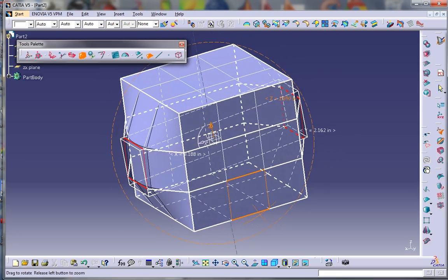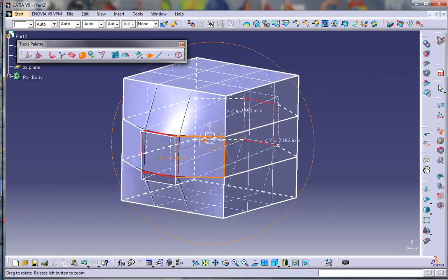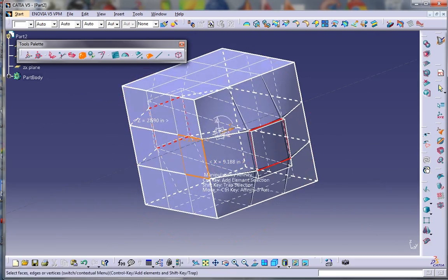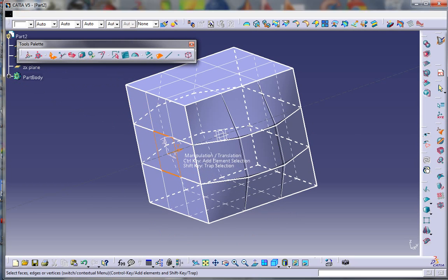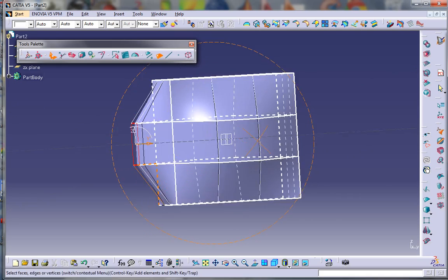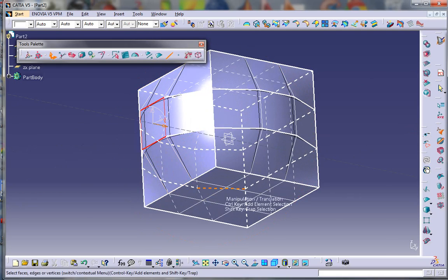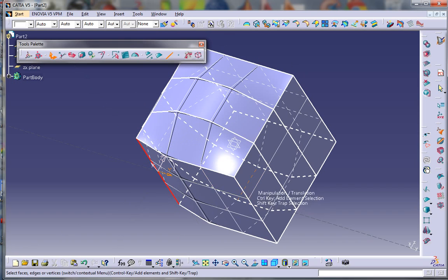Well, actually, I'm going to give some thickness to the lower part of the head. I'm going to use the translate key, and also move these lines a little bit up. So I go to the line tool and select on the Z axis. I'm going to do the same here.